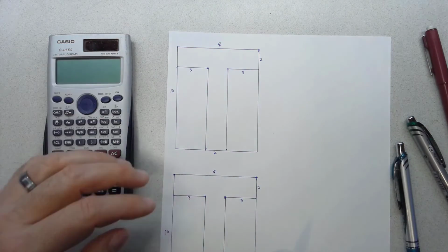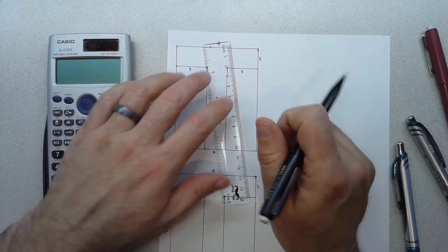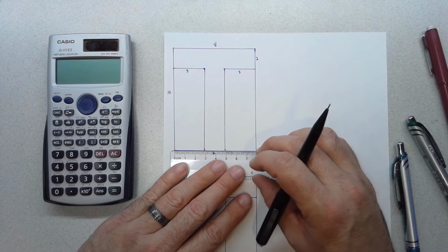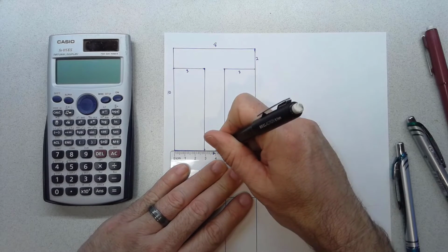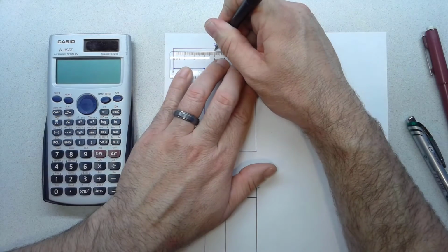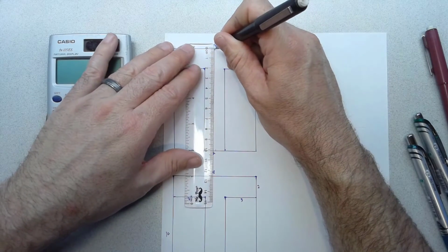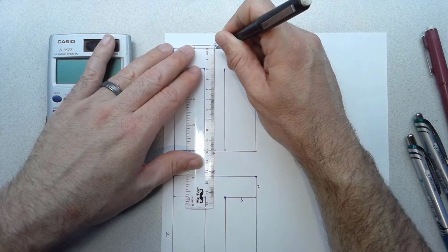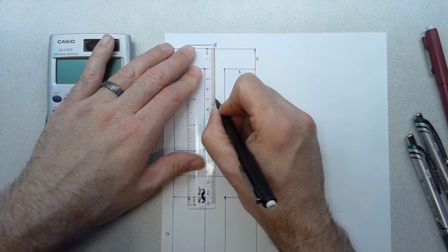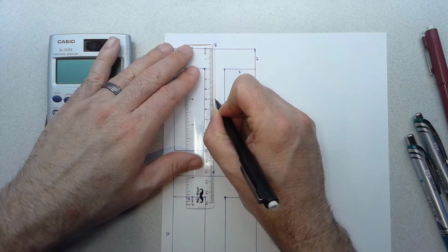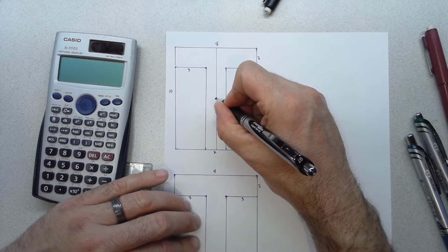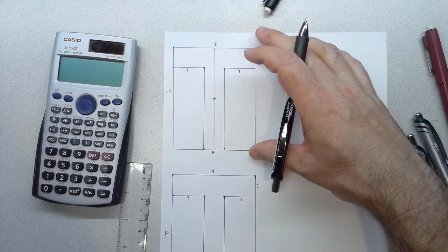Let's think about what that means before we start doing much math. Let's mark out on here the location of the centroid of the overall rectangle. Again, just like always, that's going to be at 4, 5. So 4 in the x direction, 5 in the y. So here's our one axis of symmetry. And this dot is the centroid of the whole rectangle.